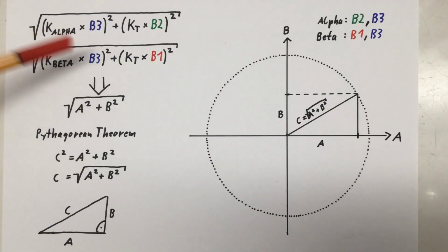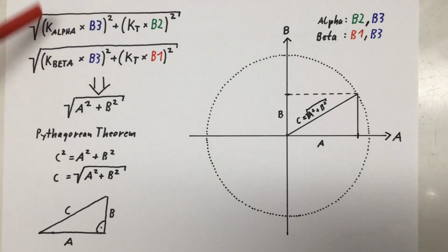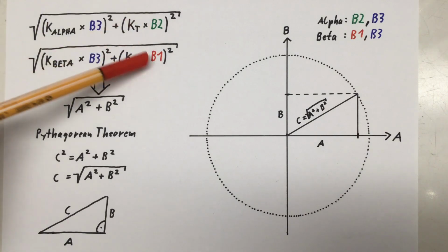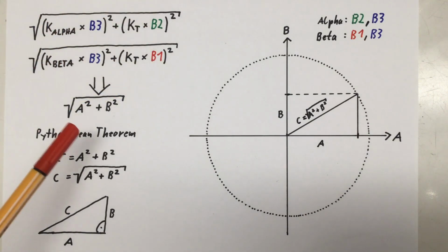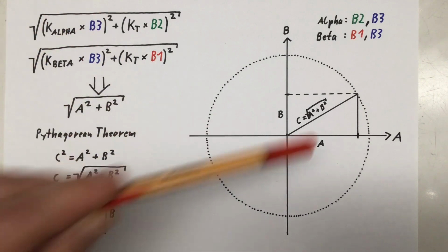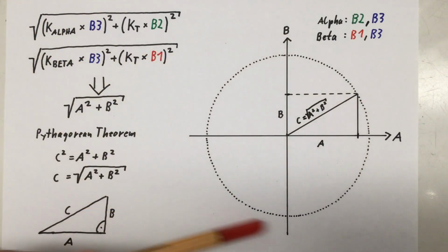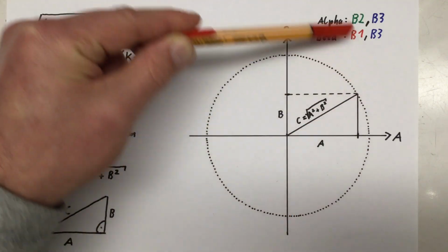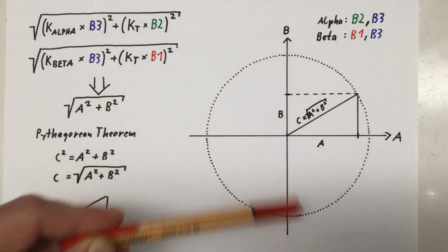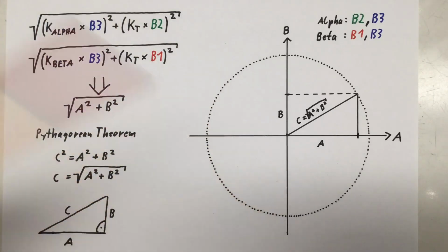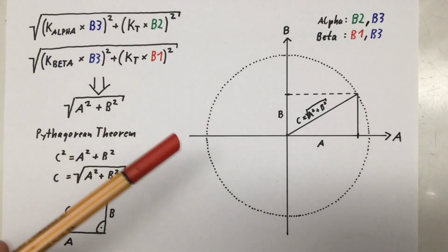We really need to scale the B3, that is Z signals, to the same levels as the B1 and B2, that is X and Y signals. Otherwise, the numerators in our angle formulas wouldn't describe a circle, but some points probably on an ellipse. And then our further angle calculations for alpha and beta go all haywire, as we have seen in the previous video.